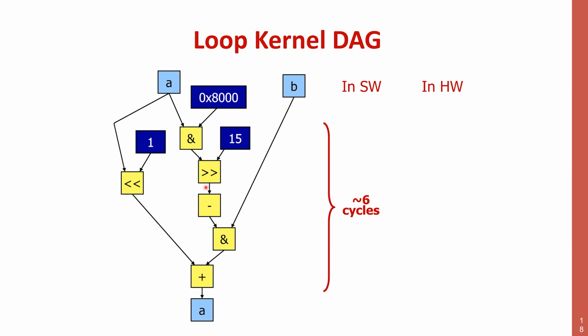Well, if I look carefully at the input, and if I remember what we said before, there is only one bit of A, the bit number 15 of A, that arrives here. Here I'm connecting this bit to bit 0, right? So bit 0 is either 0 or 1, and all the other bits are by construction 0. And now in here, I have either a 0 or a 1 that enters this minus. And so the result can only be 0 if the input is 0, or -1.